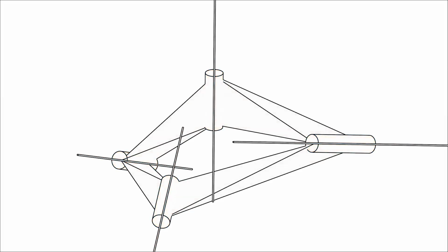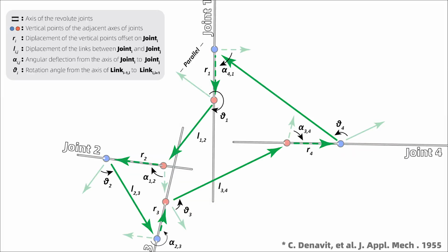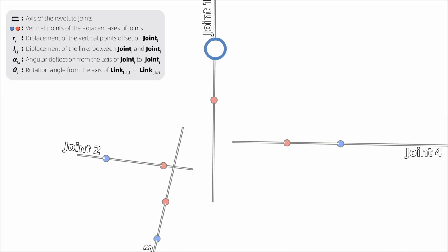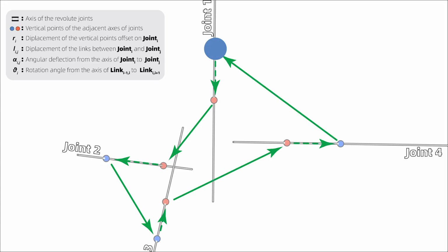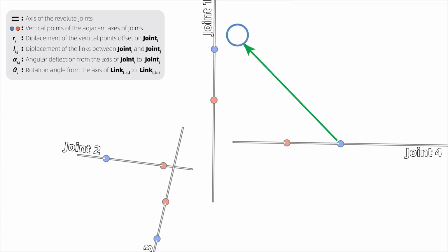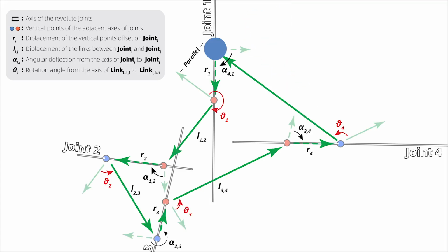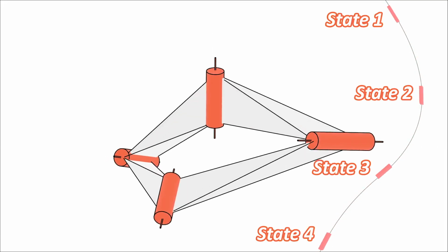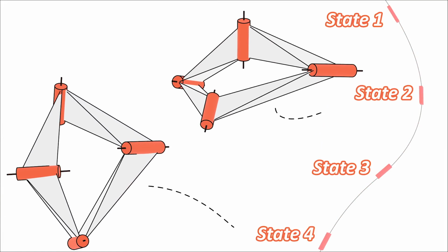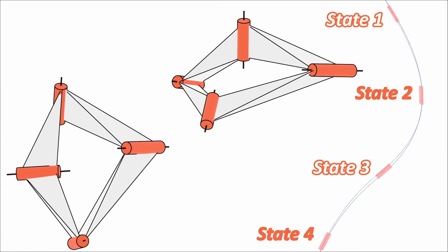The first thing is to parameterize the spatial linkage with the DH notation. And if we look again at the constraints with this language, we find they all come from the closure condition of closed-loop linkages, which, if violated, means it cannot come back to the same beginning point, and naturally the linkage would be open loop. And when the closure condition holds for all configurations with rotational angle theta, it is the continuously compatible mechanism. So decrease it down. Let it hold only for the finite states where we want the linkage to be stable. And the multi-compatibility is established there discretely.